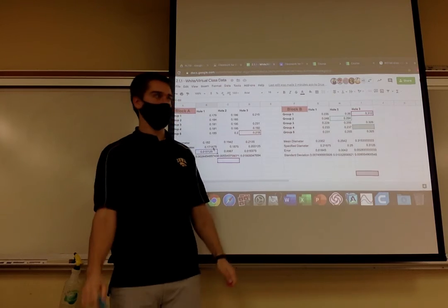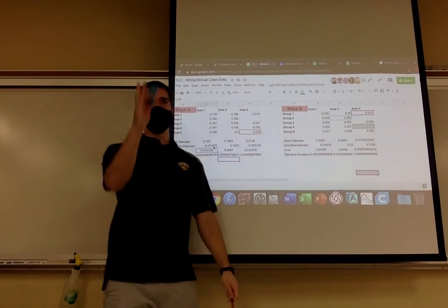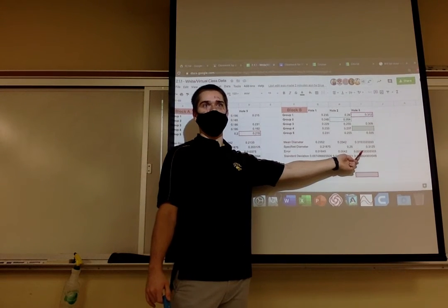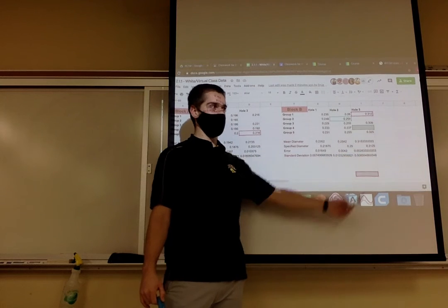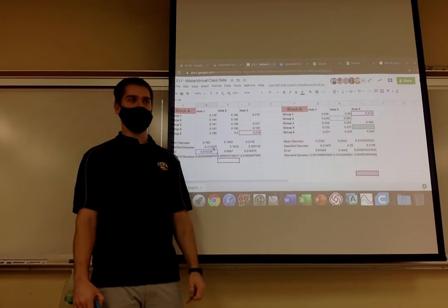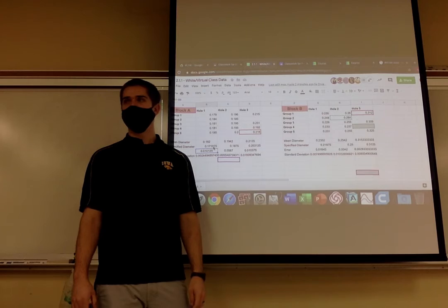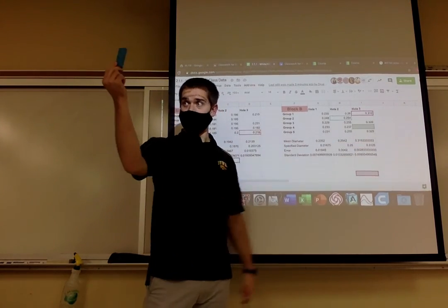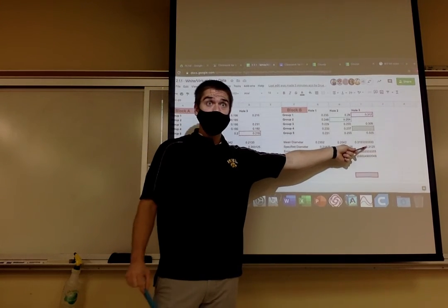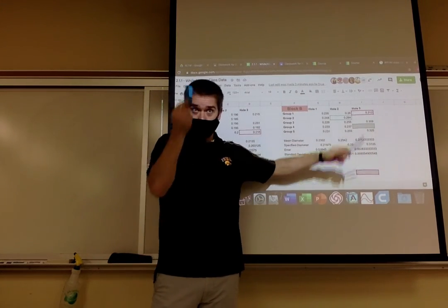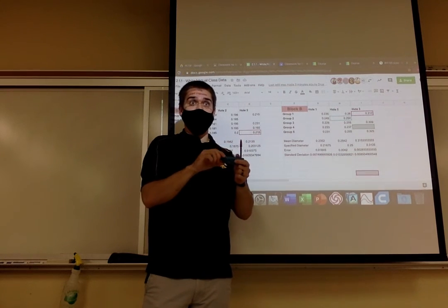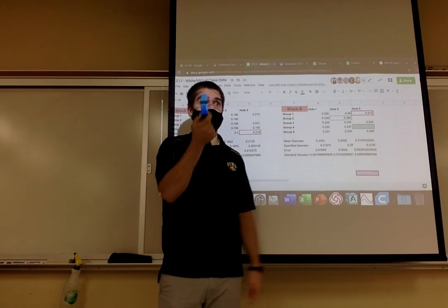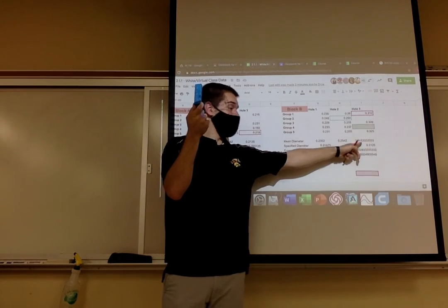Now, if I'm building a kid's building block, and I say you've got a 1/4 inch above or below, well, we absolutely meet that specification. We're 3/1000th of an inch off. That's definitely less than a 1/4 inch. So the application changes your tolerance, and I want you to see, I used a 5/16 drill bit. I literally put that bit in the drill and drilled the hole, made sure it was nice and smooth. So I made it according to the design specs. But do you see how it's not actually what it should be?